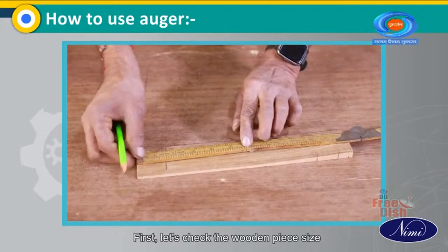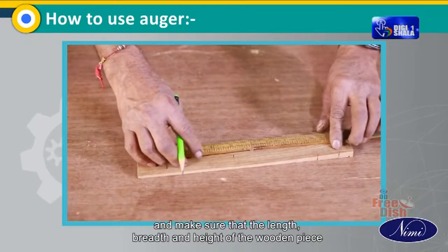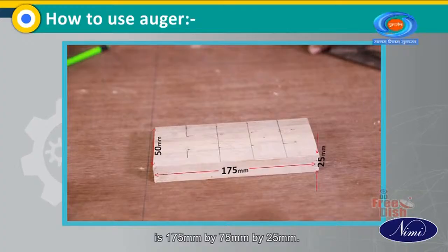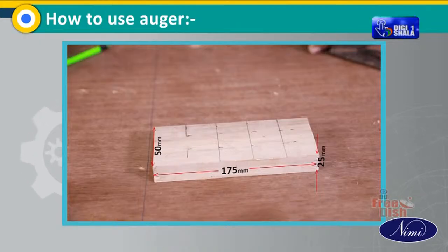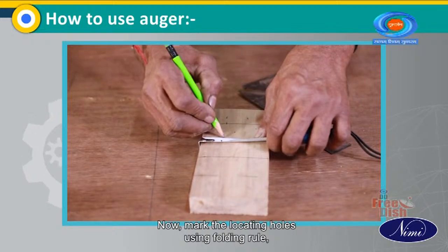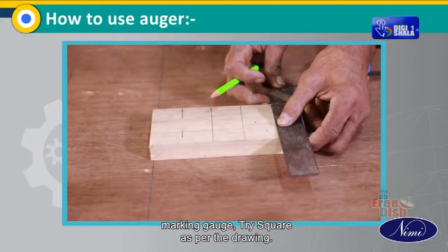First, let's check the wooden piece size with the folding rule and make sure that the length, breadth and height of the wooden piece is 175 mm by 75 mm by 25 mm. Now, mark the locating holes using folding rule, marking gauge, tri-square as per the drawing.